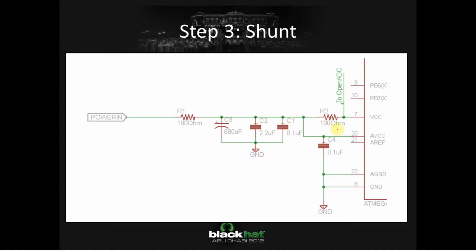The value of the shunt depends a bit on the device. If it's not taking much current, typically this means it's a more recent microcontroller, you may need something higher, like 100 ohms. If it's older, for my smart card device, I'm using like 30 ohms, I believe, because it's an older microcontroller, it takes more current. So I don't need as big a value there.